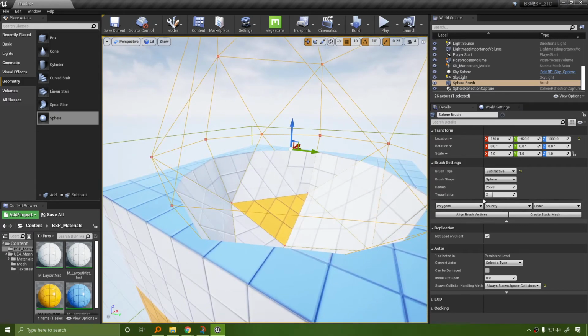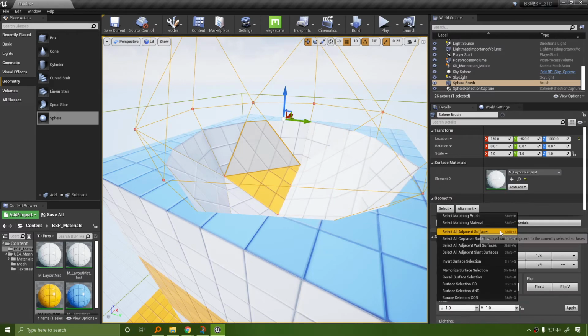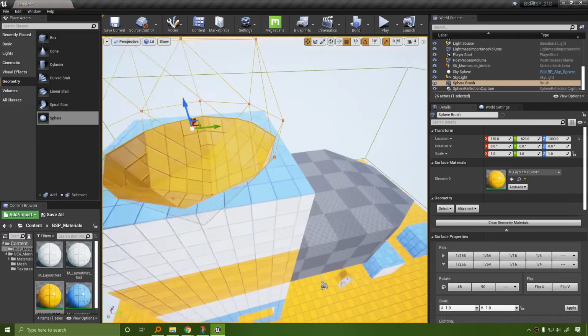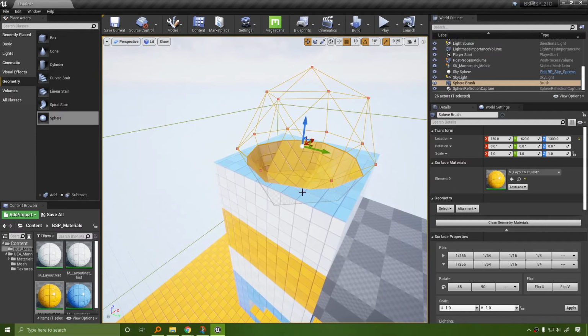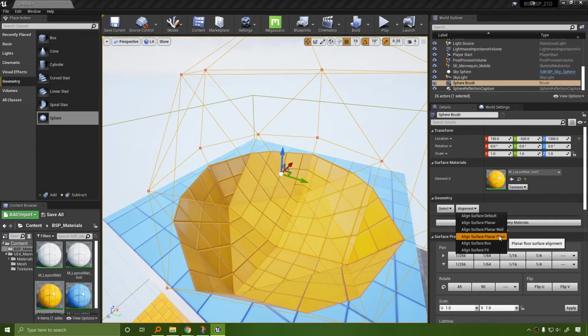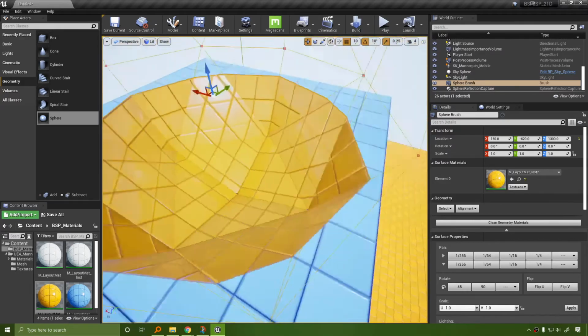Now in this particular case, I want to go ahead and select all those faces. Let's select our brush face here, select adjacent surfaces, and now let's apply our texture. So as you can see, it's very easy to denote spaces where the texture can apply. And of course, if we need to change the alignment, this probably won't have a result. Like a very mild result. You saw that it just relaxed a little bit.